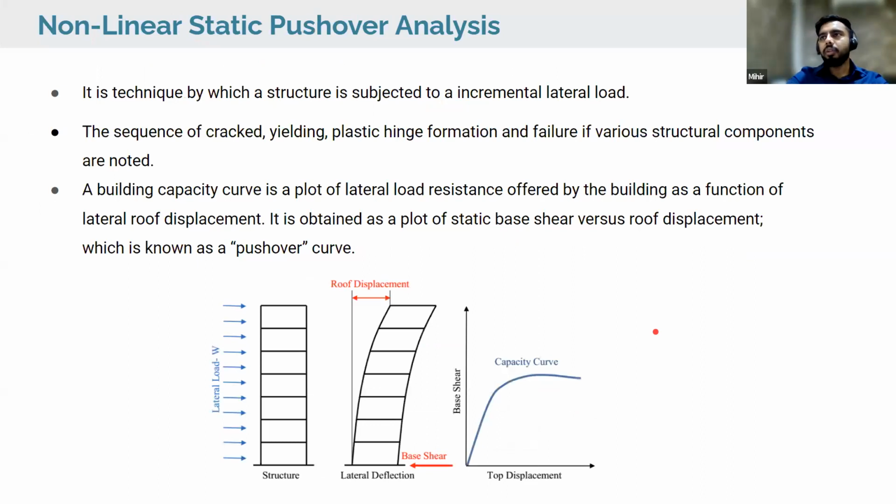Now, if we talk about the nonlinear static pushover analysis, it is a technique by which a structure is subjected to incremental lateral load. Suppose this is my building, then I'm giving some lateral load toward it, and we are seeing the deformation that is occurring. The sequence of cracking, yielding, plastic hinge formation and failure of various structural components are noted at this location.